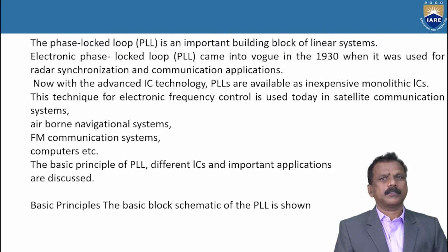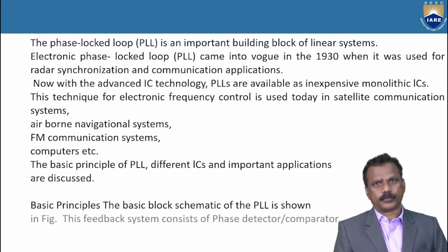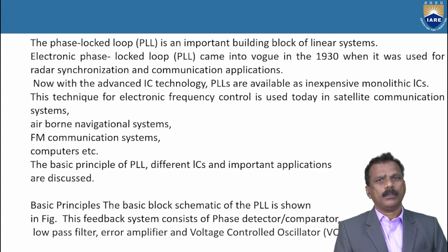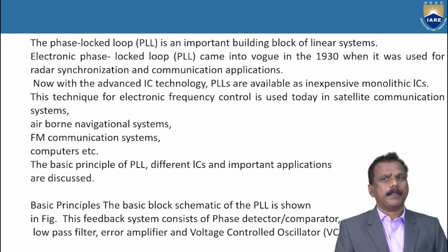Basic principles: the basic block diagram, or block schematic, of the PLL is observed. The feedback system consists of a phase detector or comparator, a low pass filter, an error amplifier and a voltage control oscillator, VCO.